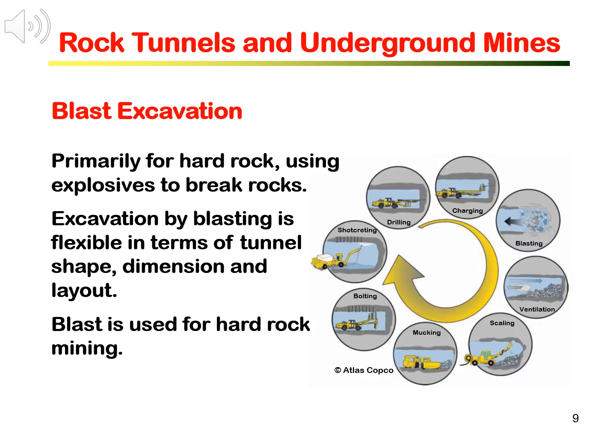Blast using explosives is still the most effective method to break and excavate hard rocks. It involves drilling holes into the rock, putting explosives in and blasting away the rocks. Drill and blast method is a cyclic excavation process.